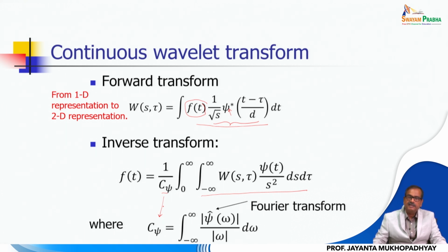One of the things you should note for the wavelet transform, as I mentioned, is that in ordinary non-wavelet transforms, for example Fourier transforms, there was a single parameter, like only frequency, even for a one-dimensional transform. But with wavelet transforms, since we are trying to localize both in space and frequency, you have two parameters.